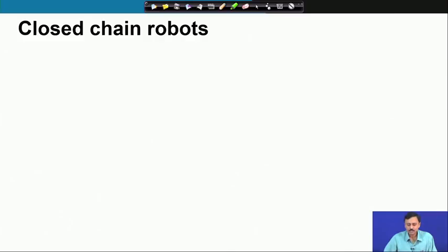So, here we have a nomenclature which I am going to explain. What are closed chain robots? They are also known as parallel manipulators. In normal robots, as we have an idea of, we talk of serial chain manipulators. For example, my hand you can consider as a serial chain. Why do we consider this as a serial chain? Because the actuators and the joints appear serially in the chain. Here there is one joint which is actuated, here is another joint which is actuated, and they come serially.